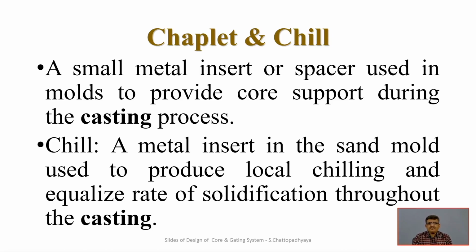What is a chaplet? A small metal insert or spacer used in molds to provide core support. A hanging core, how will it be hung in a concentric position? The chaplet is the candidate to do that, and that will also melt away after doing its duty to keep it in a concentric placement in the core after the pouring of the molten metal.